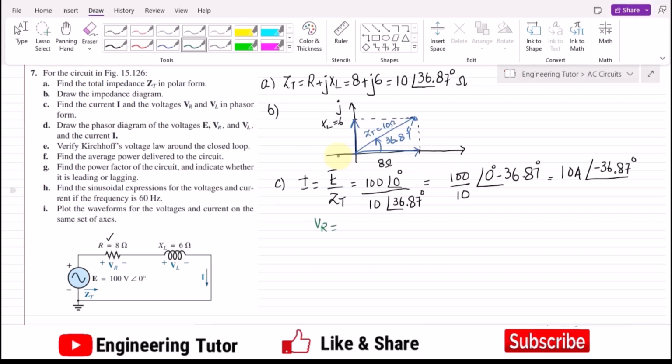As this is a series circuit, the same current flows through both elements, and that current is I. So I multiplied by R: the value of I is 10, with the angle minus 36.87 degrees, multiplied by R, which is 8. That would be 80, and the angle is minus 36.87 degrees, in volts. This is V of R.